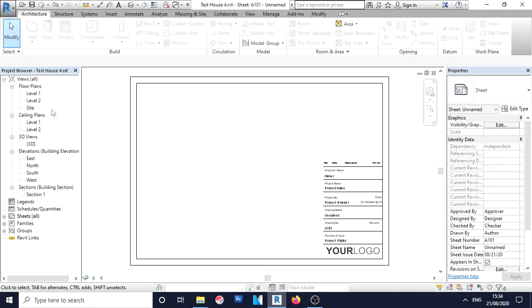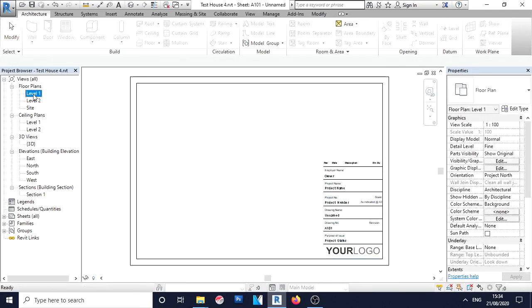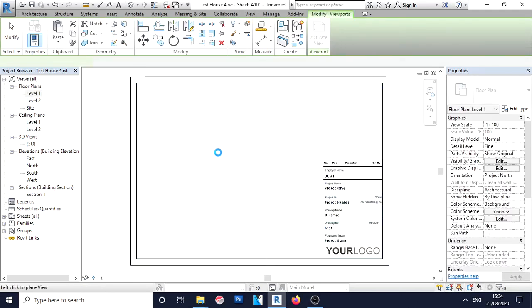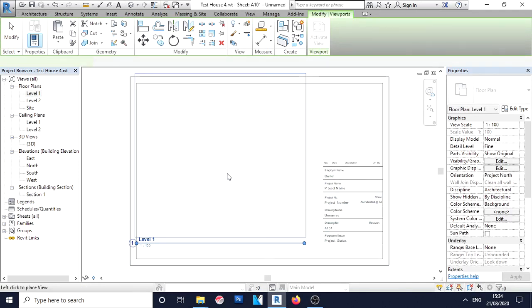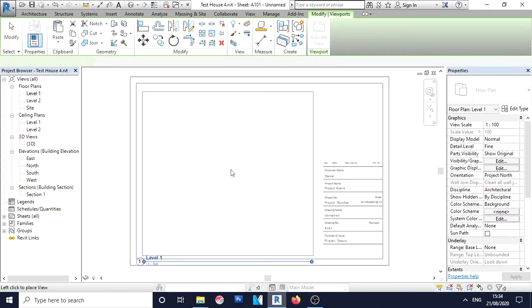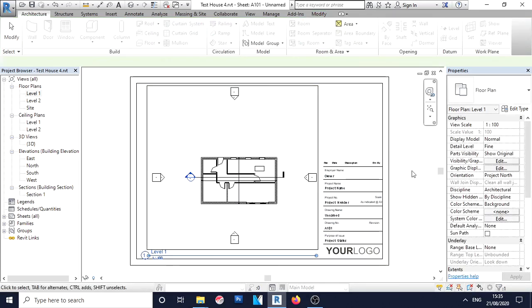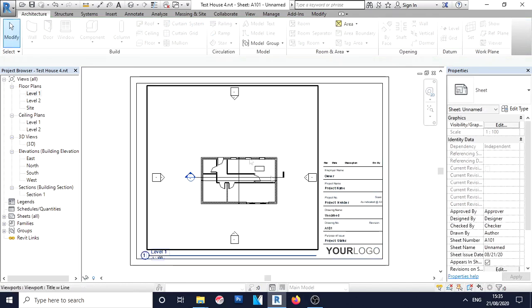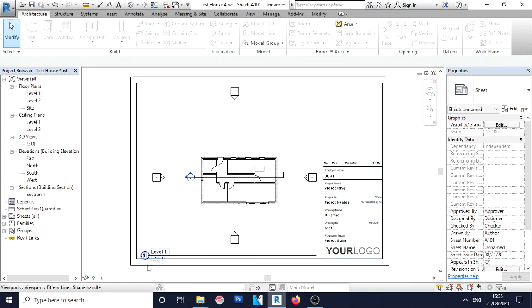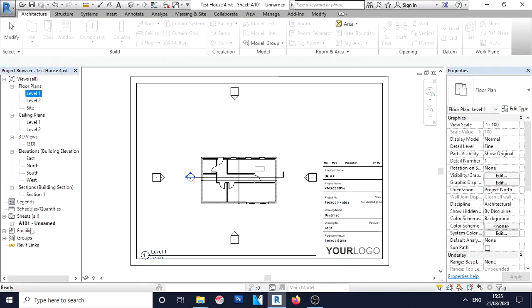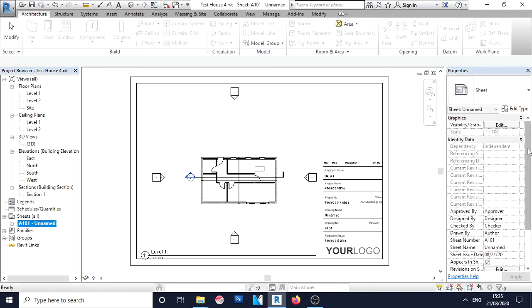The next thing you might want to do is to put some information onto that sheet. You can simply drag your views into that sheet now. Just giving Revit a moment to process it. And if they're the correct scale for that type of sheet, they will fit. You can then modify that. So now you have a sheet set up. It should draw project information, and it also has a drawing on it with scale. When you go to the sheets, you should see it here, automatically named, and you can simply modify that in the Properties toolbar on the right.